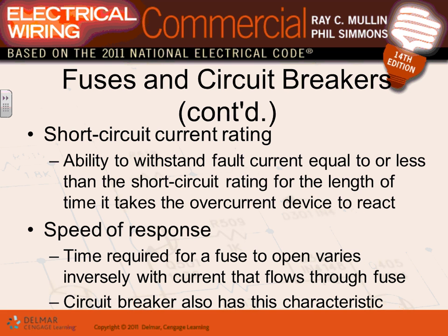Short circuit current ratings. There's an interrupting rating, Karen and Derek, my friend, and a short circuit rating. Interrupting: you have a fuse, how much can this fuse handle before it explodes. Withstand rating, or short circuit withstand rating, is for a conductor: how much short circuit can this conductor handle before it burns? Because conductors don't interrupt the current. So the withstand fault current must be equal to or greater than the short circuit current.